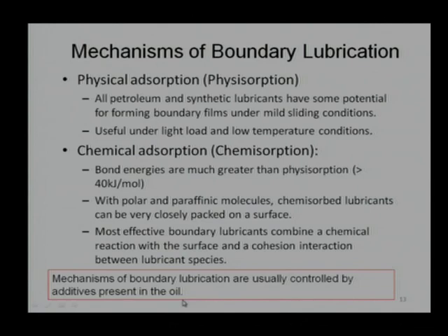That is why we say that whenever we try to use a lubricant, it should be studied properly. It should not happen that, knowing chemical absorption is a good event that can sustain high temperature and high load, we mix 5%, you mix 10%, you mix 15% of this kind of additives. If we keep on increasing the percentage of additives, it may be much more harmful compared to not using that kind of lubricant additive. And we can say that this kind of boundary lubrication mechanism can be controlled by adding additives in oil, which I explained earlier.